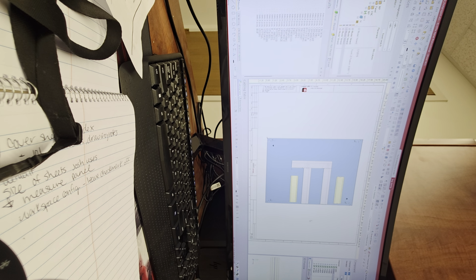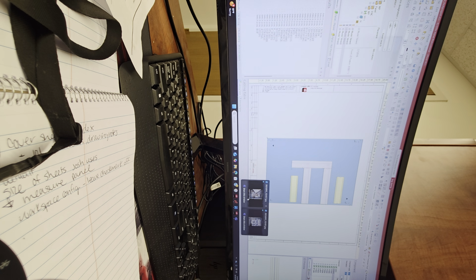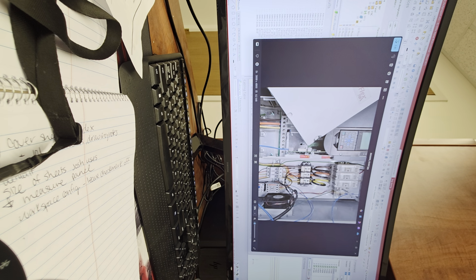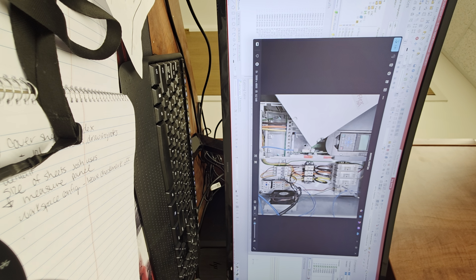And then open up your picture one more time. What's some random device that we can mimic from that design? Is it a circuit breaker that you had on top? Yeah, there was a disconnect. All right, I'm not sure what those first 3 devices are. What is that? This is a disconnect, a fuse, disconnect and distribution block. The disconnect is the one with the rod. Yep. Then we have the power distribution, circuit breaker or a contactor on the bottom right.